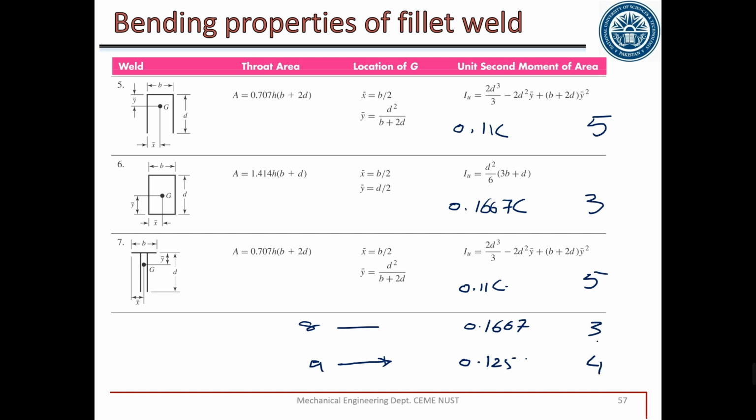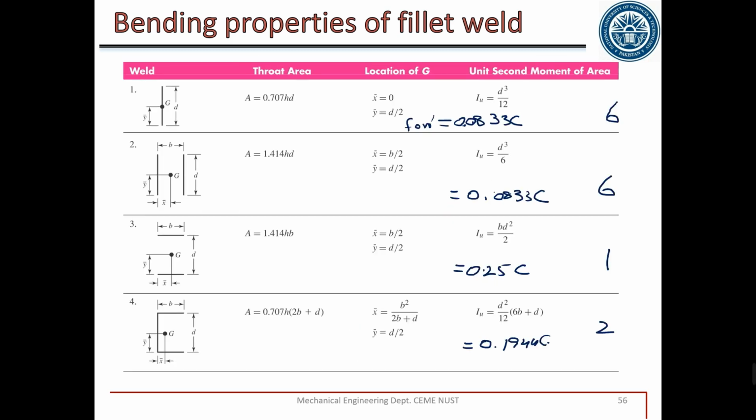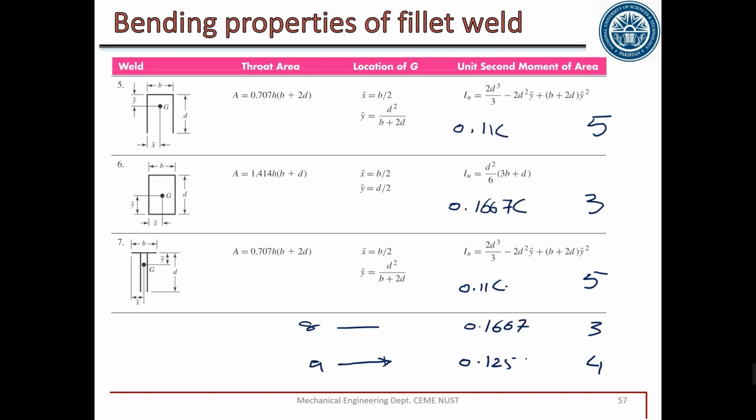So if we have a case of bending and we have a cross-section area of A cross A, then the best choice to use is this parallel weld. And this square weld is at rank 3. So if you see the previous case for bending, this all around square weld and parallel weld had same rank, first rank, but for bending this has the lower rank.